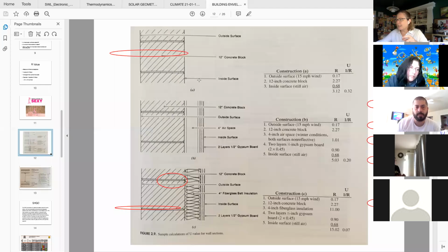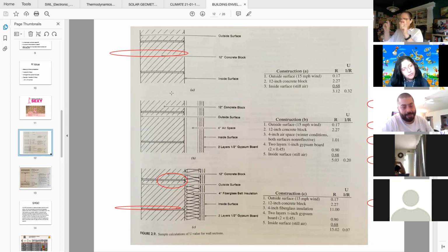You need something to attach it to. You don't want to be attaching drywall with concrete screws to a concrete surface wall. It's much easier to use a drywall screw into a piece of wood. And then you just have the concrete screws for your wood furring into your block wall.